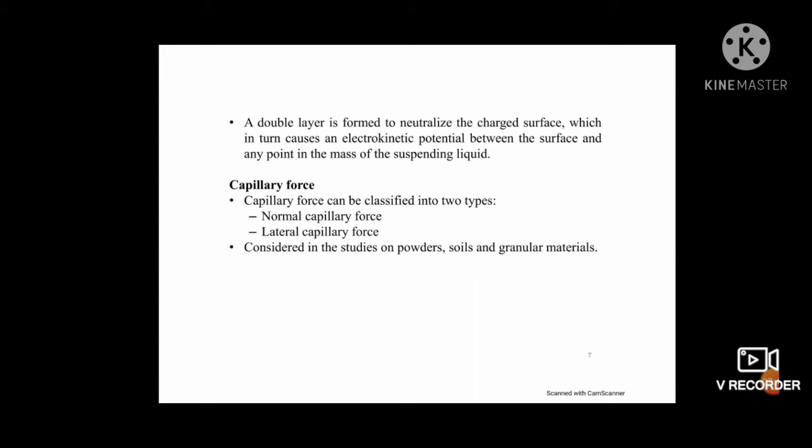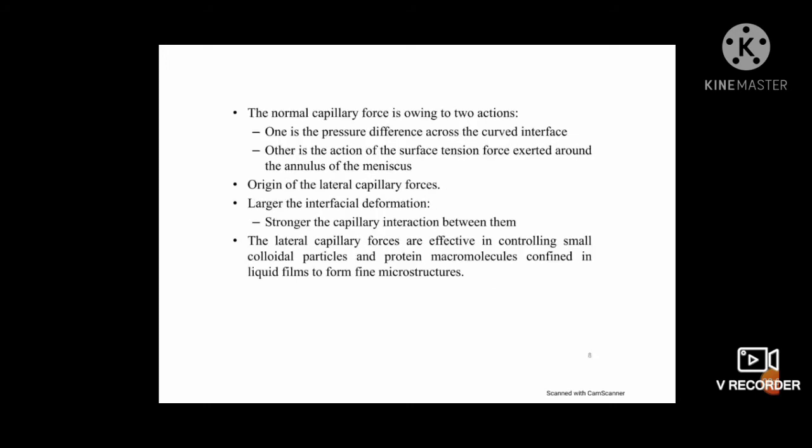Third is capillary forces. Capillary forces are due to the meniscus, and are also known as meniscus forces. Capillary forces can be classified into two types: normal capillary forces and lateral capillary forces. These capillary forces are studied in powders, solids, and granular materials. The normal capillary forces are due to two actions. One is the pressure difference across the curved interface. The other is the action of the surface tension force exerted around the annulus of the meniscus.